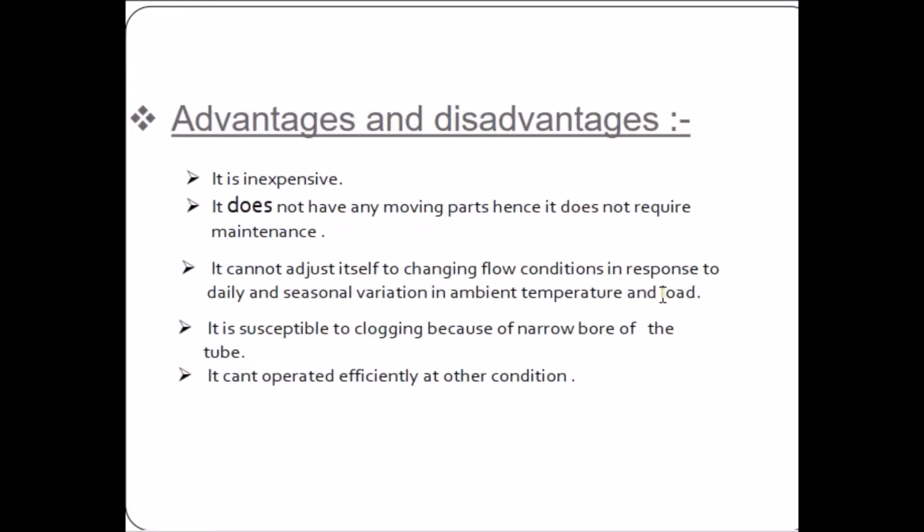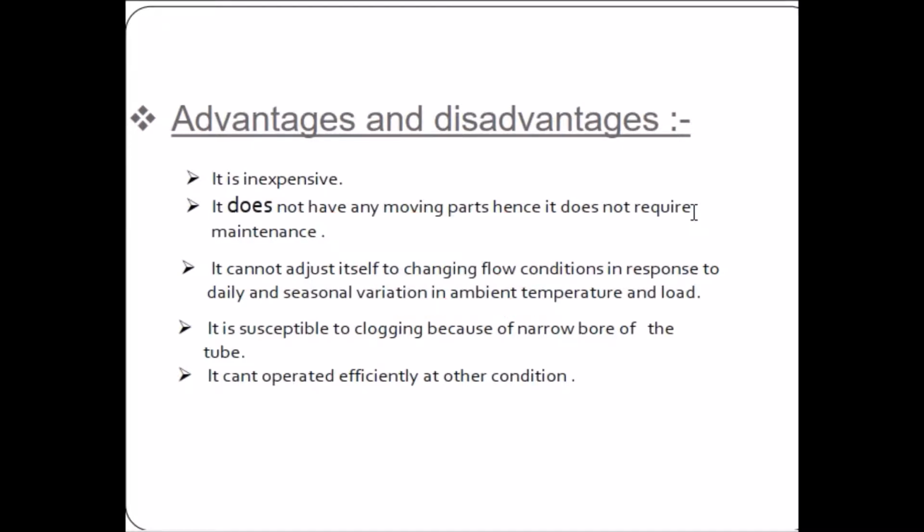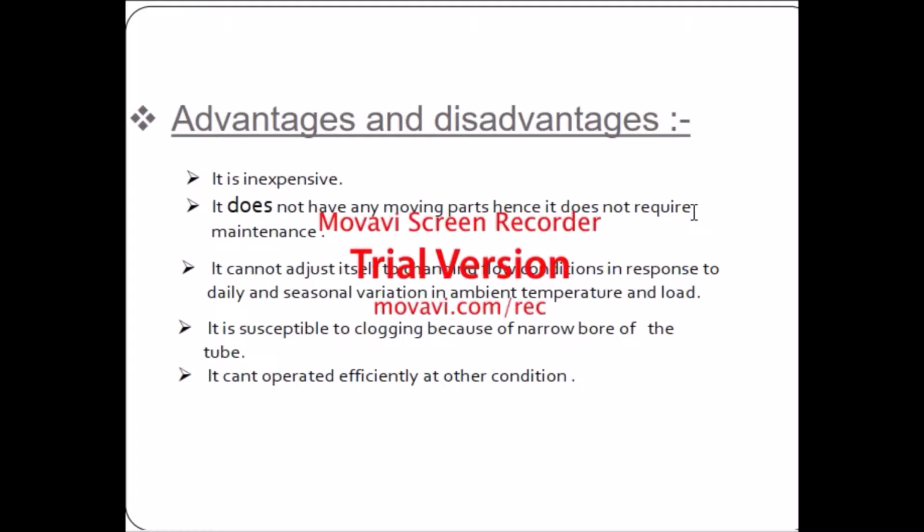Okay, actually we cannot control the temperature by the ambient environment, because in the capillary tube the pressure drop is already achieved by using the reduced tube diameter, so we cannot control it by ambient environment change.